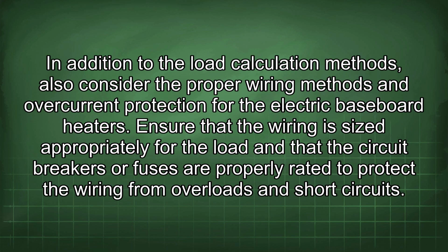In addition to the load calculation methods, also consider the proper wiring methods and overcurrent protection for the electric baseboard heaters. Ensure that the wiring is sized appropriately for the load and that the circuit breakers or fuses are properly rated to protect the wiring from overloads and short circuits.